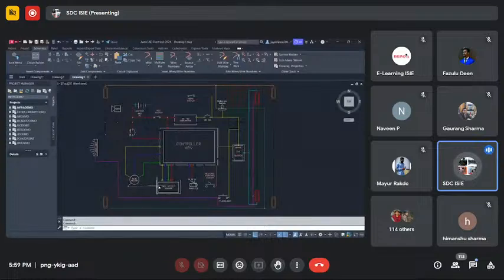While the BLDC motor is inserted, we have 3 Hall effect sensors. So these 3 wires, yellow, blue and green, are for the Hall effect sensor connections. Along with that, we have the throttle connection from the controller, and a different approach of DTC FOC connection for a brake cut switch also.